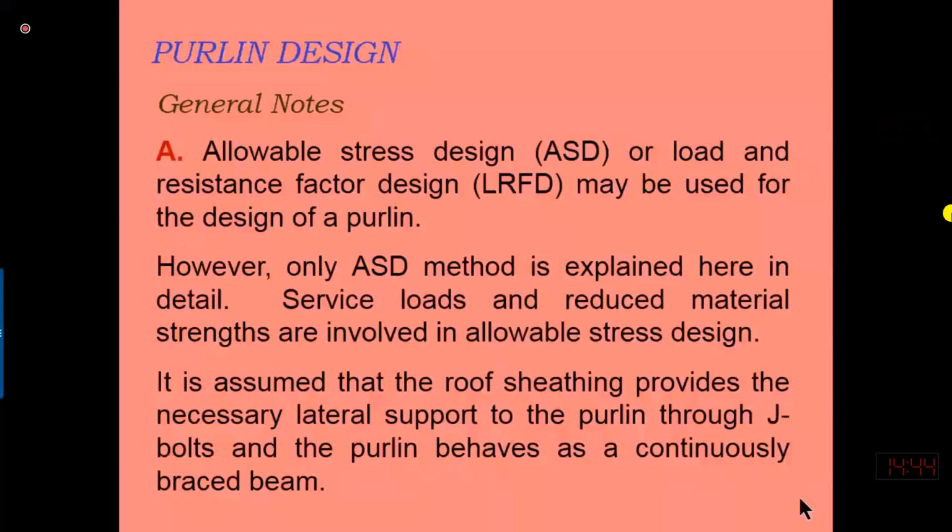So they are preventing any load which is directly coming on the member, or in between the truss members, to avoid any bending moment. So purlins are beams resting on two panel points of trusses, and they are transferring all live load and dead load at a panel point.